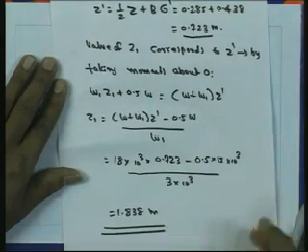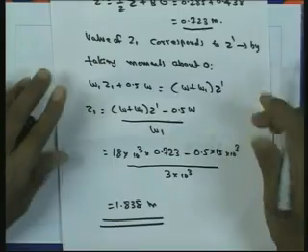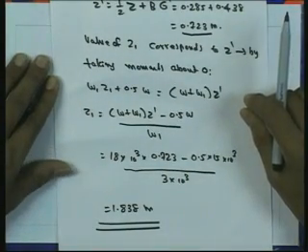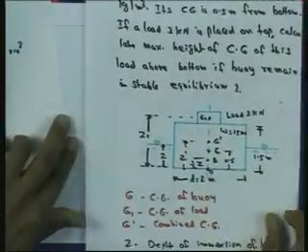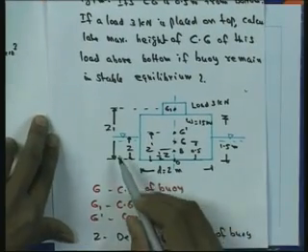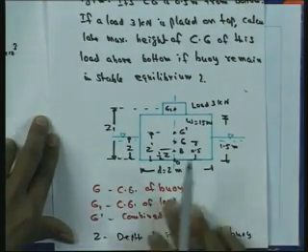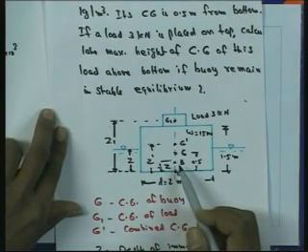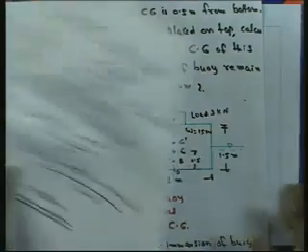So finally, we get Z1, from the bottom of the buoy to the center of gravity of the extra load, as 1.838 meter. In this figure we have determined Z1 as 1.838 meter and Z dash as 0.723 meter. This gives the solution of the problem.